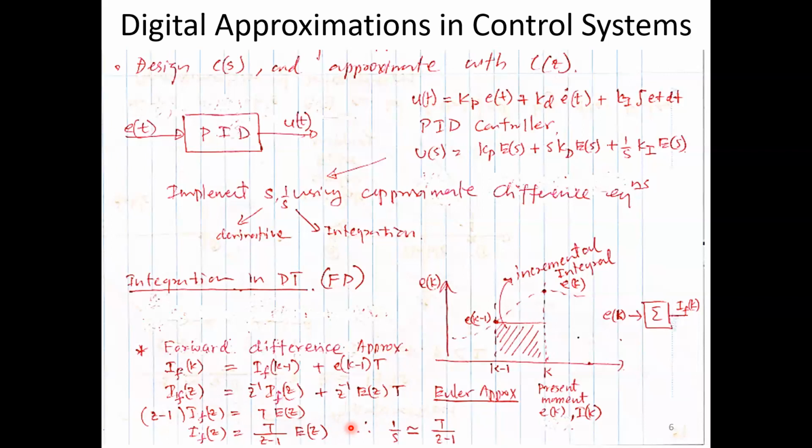On the left hand side, the integral of the error. On the right hand side, the error. So this is the integrator, therefore. So very much like this. You have error going into a block, and what comes out of the block is error integral. So this is the integrator then. It's summing up error times time, error times time, error times time, and updating the integral.